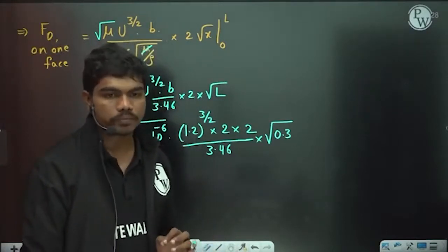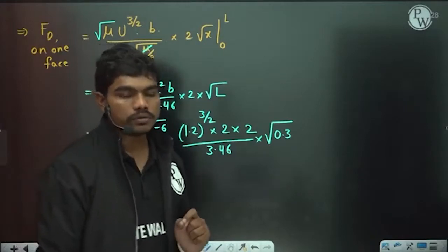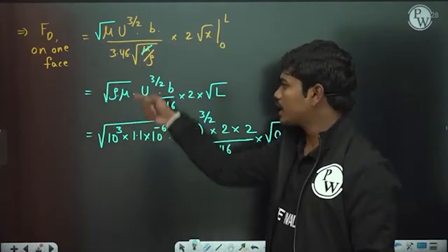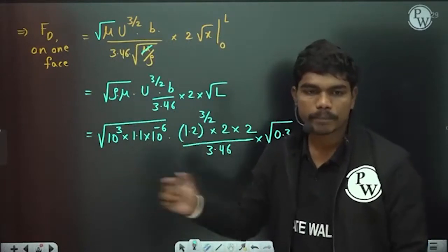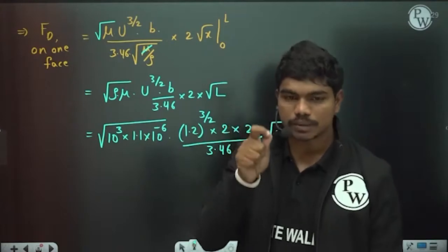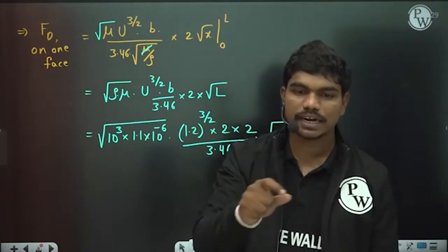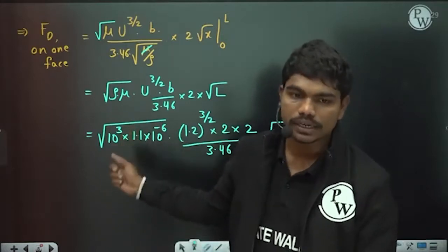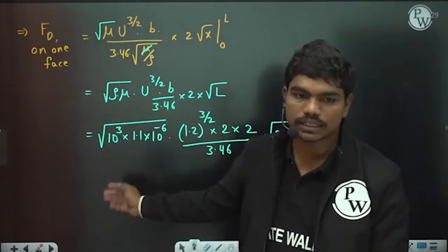So please type in the chat box. Is this clear to you? All of you? Did you all understand this expression? How did we achieve this and how have we written these values? Basically, if you know the wall shear stress at some location, then that wall shear stress is multiplied by the area available for the fluid-solid contact. So tau W into B dx, we have done this analysis. Clear?